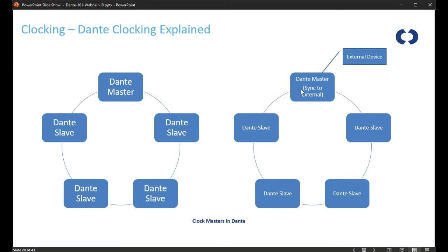Now, I'm pretty sure that makes sense in a way, but a few scenarios. I have a Blue 806. It's the most reliable DSP. I like its clock. I want to use it. I click sync to external. Then that will be the clocking device for the Dante card in my Blue 806, and then that will distribute the clock for all the other devices in the Dante system.